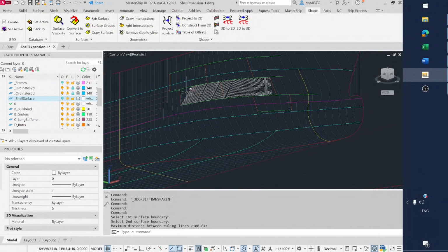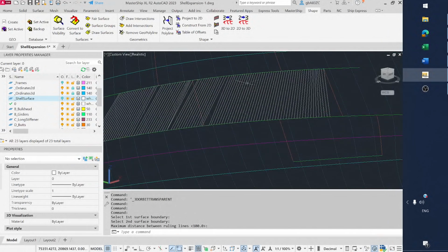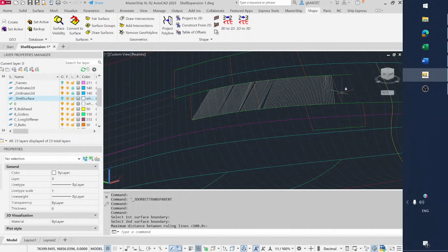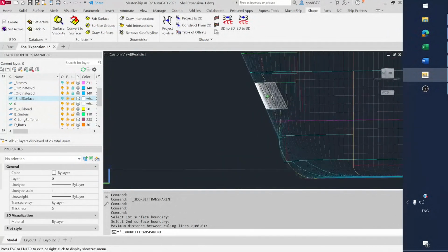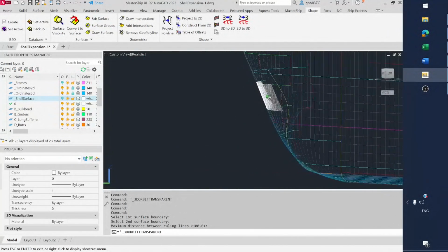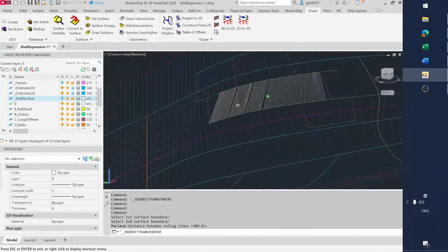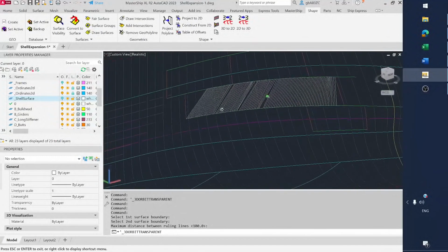And then we see all the rulers. And those rulers indicate where the plate can be bent to get a single curved plate. Since they are not crossing anywhere, that means that this plate is developable, so it's single curved. So we can also check this visually. If we look at it like this, then it indeed seems to be the case that this plate is developable.